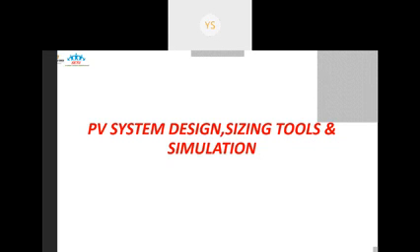Then we go for the pre-feasibility study. In a pre-feasibility study, you go to the site, find out the location and how much the radiation is. The most important thing in the pre-feasibility study, if you install a solar power plant, is that the area is always shadow free. If some shadow falls on that particular location, your module is not working in an optimum condition.